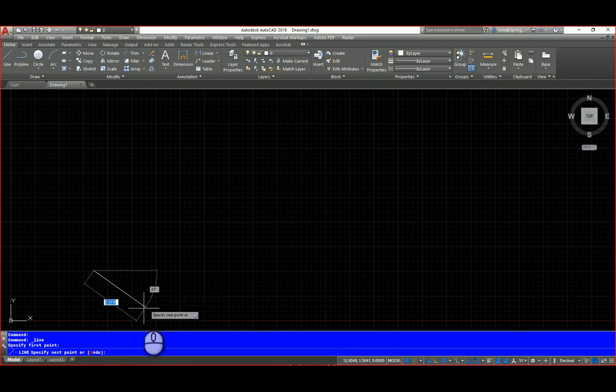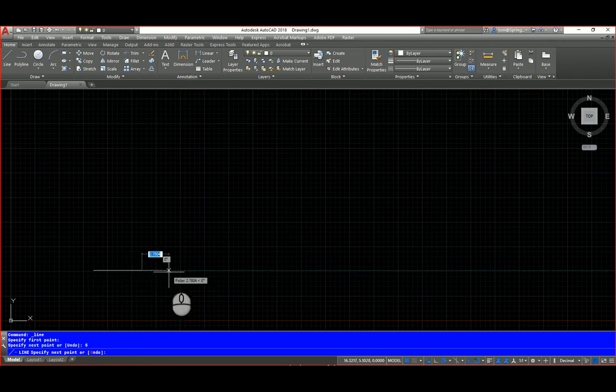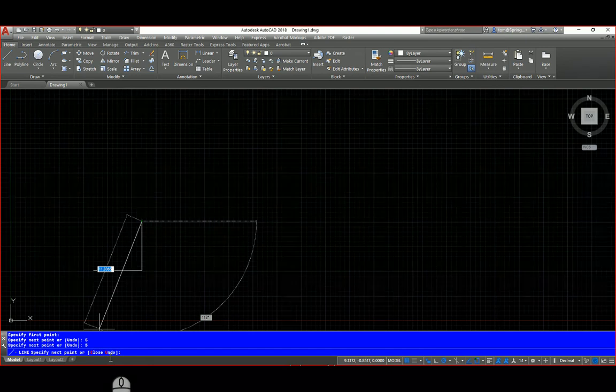And look at your command line, it tells you what that choice is, or undo. The word undo is here. The U is capitalized, meaning that if you type the letter U, it's going to invoke that command. Also, it's highlighted in red, so that tells you what's going on there. So if I were to go over here and type in, let's say 5, hit my enter key, well now it still says this or undo. I'm going to type in 5 again. Now once I've done this, notice that there's yet another option. I've got close, and now I have undo. Close is new. That means if I choose the close option, it'll close this object, okay? And I've got undo here as well.